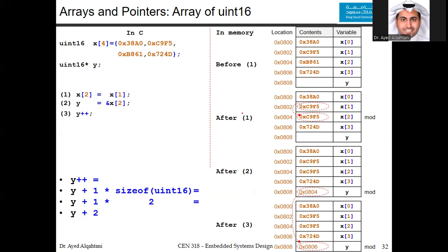And it's also obvious when you see the locations. This is 16 bits. Each variable will accommodate 2 bytes. So the starting one is 0x800. And remember, we said that the variables in the microcontroller start with this position. We can put the first variable here. So you have 0x800 accommodating 2 bytes.